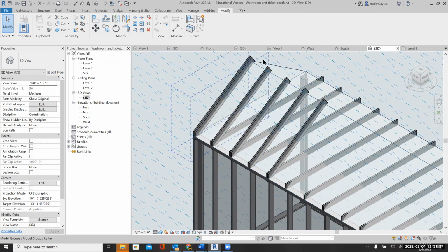We have to also connect the rafters at the top. There's a few different ways to do it. You could put a ridge beam in. You could overlap the rafters and nail them together. But each of them presents some kind of problems. Probably the ridge beam is the best way, in which case you'd need to use another void to cut off the top of the rafter so it fits around the ridge beam.